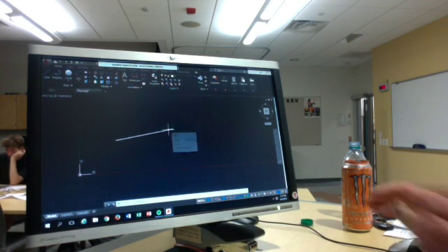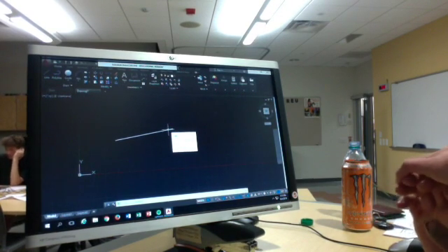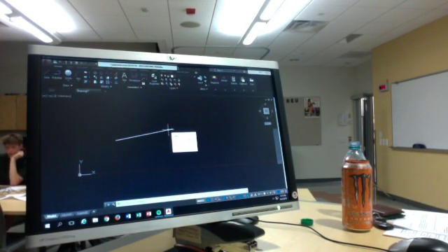Okay, yeah. So a drawing file, that's your .dwg. That's what you're actually working on. The DWT is kind of the foundation of it. So when you go to start a new drawing, you choose a .dwt file because it loads all of the dimensional properties and units properties and the actual borders that you're going to work with. Then once you save that, it becomes a .dwg and it's specific to what you're working on.